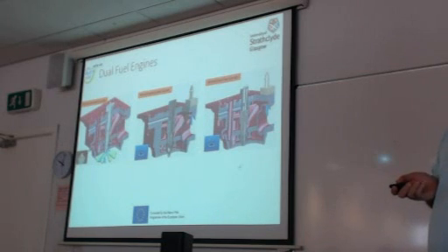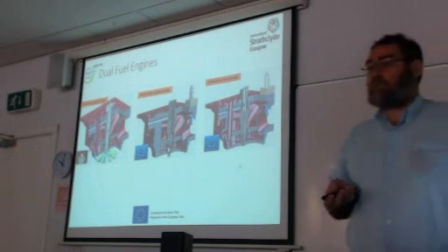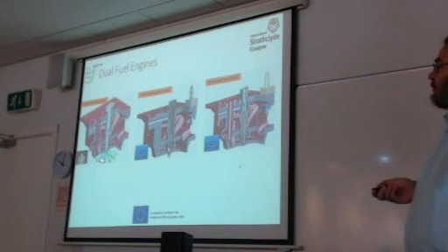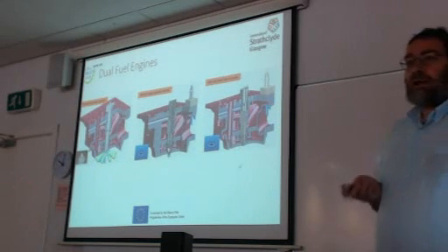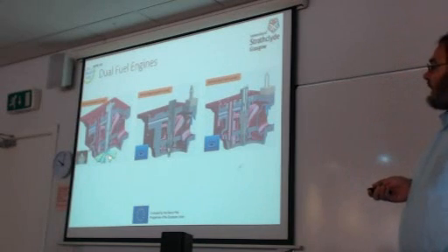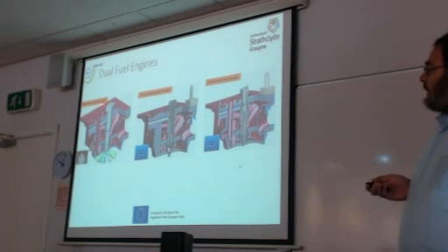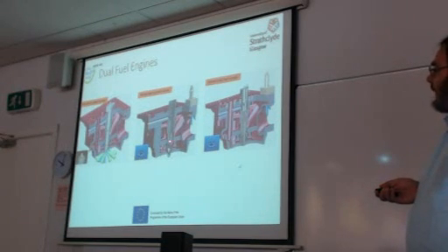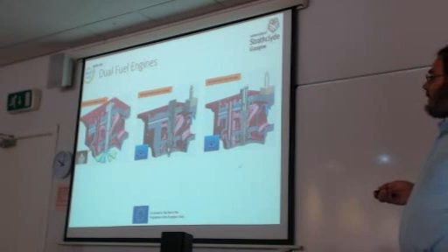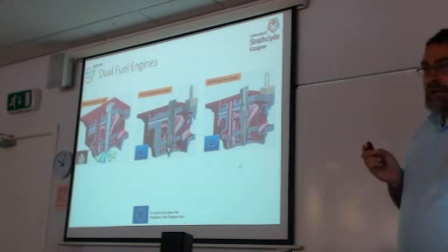So we have the diesel gas concept, usually GD. In the diesel gas concept, the engine operates in diesel mode, but instead of only diesel, the blue jet denotes diesel fuel. The green jet denotes natural gas fuel. In this case, natural gas is injected at the same time with diesel fuel. So we have a combustion of natural gas and diesel fuel. So this is the diesel gas concept, GD.